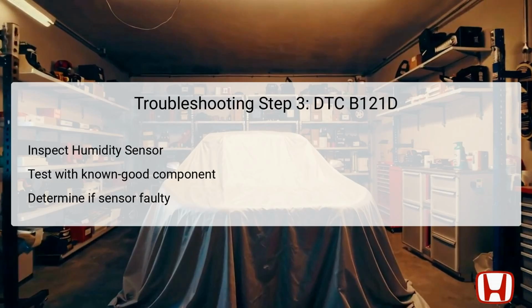After installation, you should attempt to reproduce the failure by checking if the DTC reappears. If the fault disappears and the sensor functions correctly, it indicates the original sensor was malfunctioning. However, if the symptoms persist, it suggests that there may be related components causing the issue. Document your findings systematically to ensure thorough diagnosis.